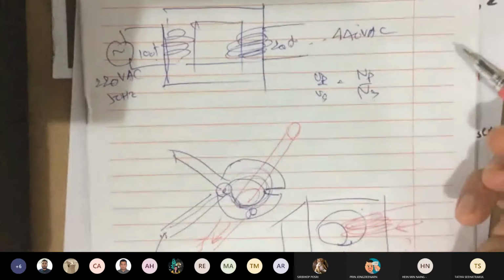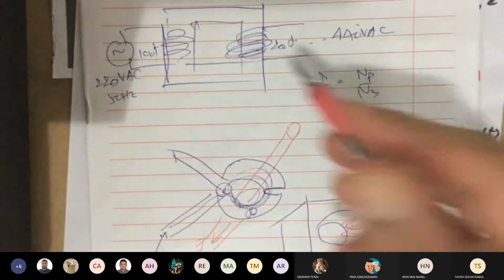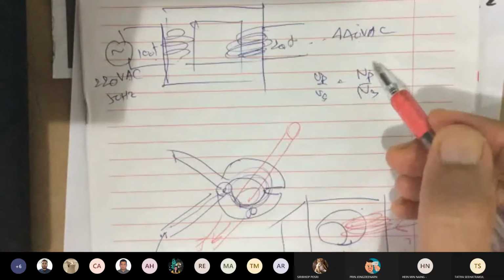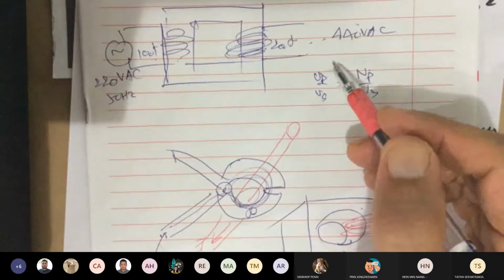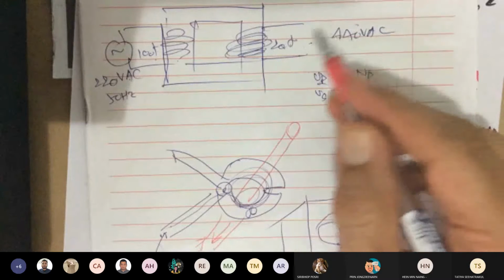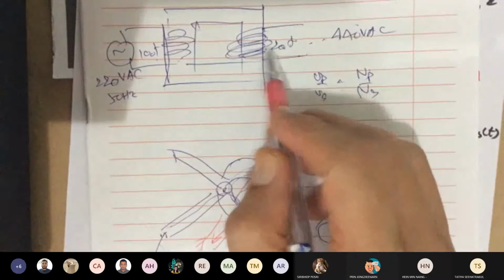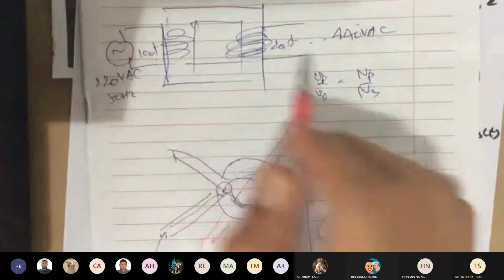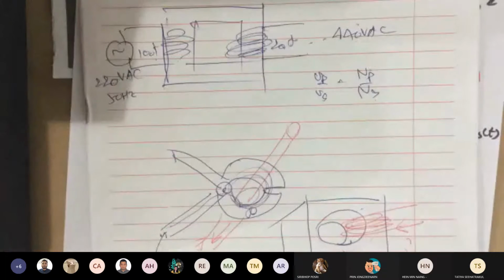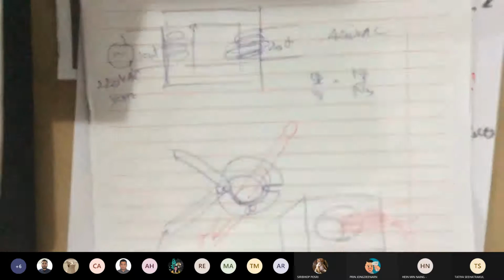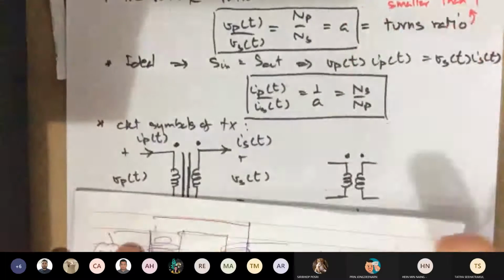See? This applies to real transformers, which we'll explain later, but this is true for ideal. No matter how much voltage you want, either step up or step down on the secondary side, you just change the number of turns of the secondary, or you just change the ratio between the two. You see how easy that is. You don't even need a calculator to do the calculations for the number of winding turns. So this is the voltage ratio.